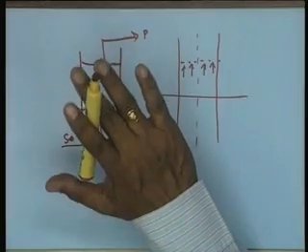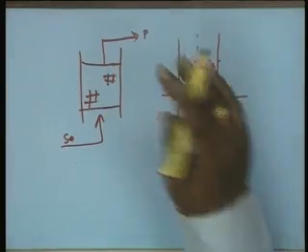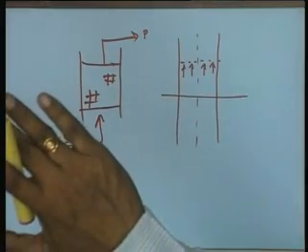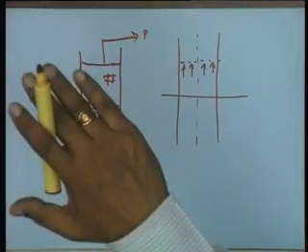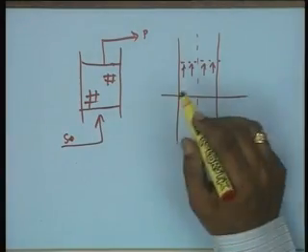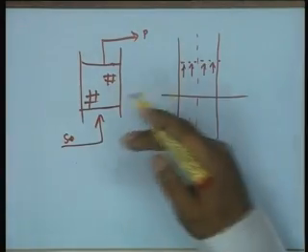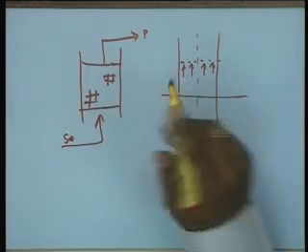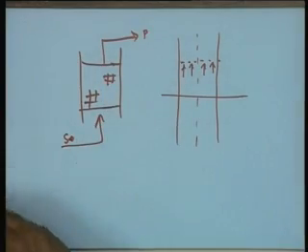That means there are no axial dispersions, and so the velocity profile of the feed stream throughout the length of the reactor is flat. In other words, the feed stream moves almost like a plug, and therefore the name plug flow reactor. Broadly, they are essentially packed bed systems, and they can be operated.